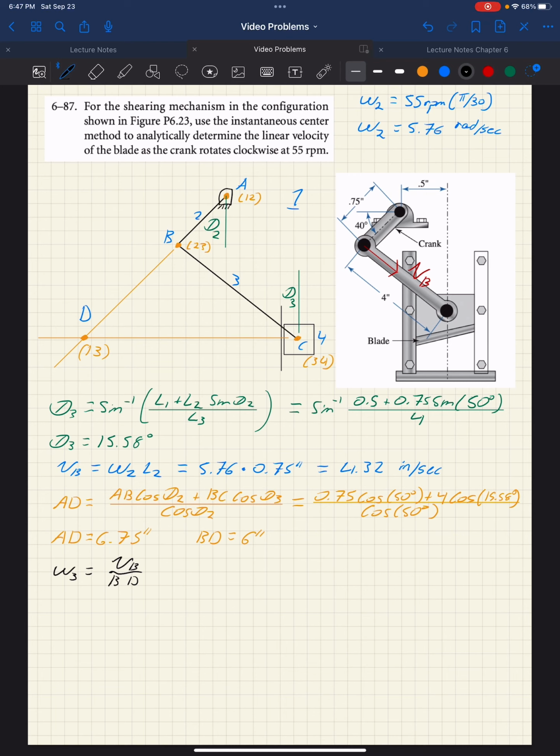All we're doing is shifting our equation around, right? We just solved for the velocity of B; velocity of B was equal to omega L2. But we know at point D, that is an instantaneous center of rotation, as we're observing from link 1, we're observing link 3. So it looks like link 3 is in pure rotation, so we can treat it as though it's pure rotation.